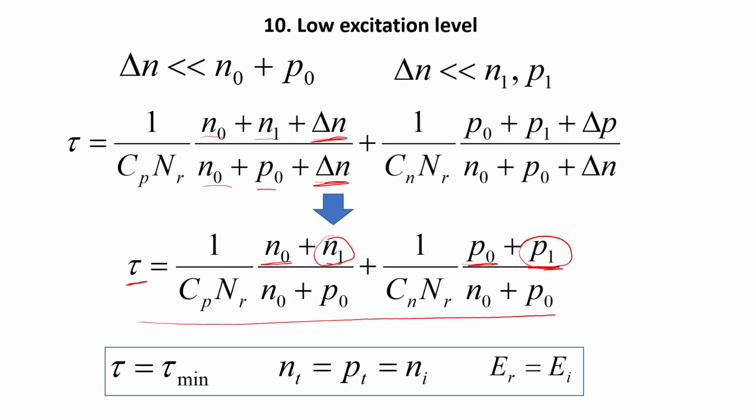Technically zero, but if we are talking about not zero Kelvin temperature, like room temperature, then it will be determined by the band gap, meaning it will be equal to intrinsic charge carrier concentration. There is no option to get lower charge carrier concentration because we have a band gap and there is some thermal activation from valence band to conduction band that will result in some intrinsic charge carrier concentration. So the minimum value for N1 and P1 will be Ni.